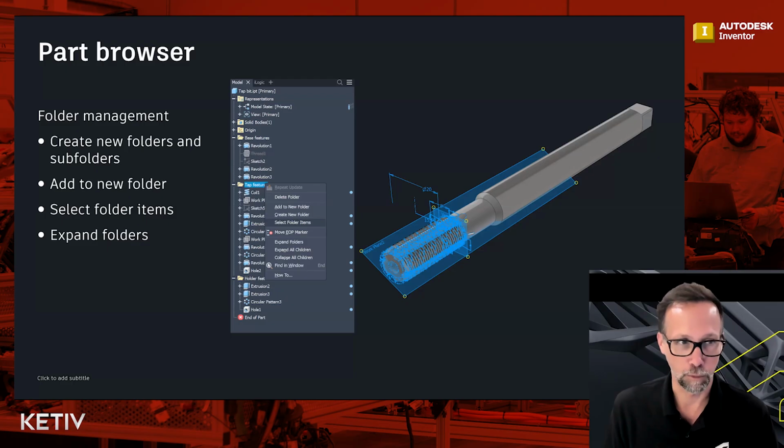One of the things that's worth remembering here, though, is that the order of the features that you have in the tree is still important to your design intent. So there's going to be times where you can't drag a feature into a folder because it just simply won't allow you. For example, you can't drag a bottom feature in your tree above your base feature, and so that's still going to play a role. But again, this is a great enhancement for those of you that have very long feature trees.